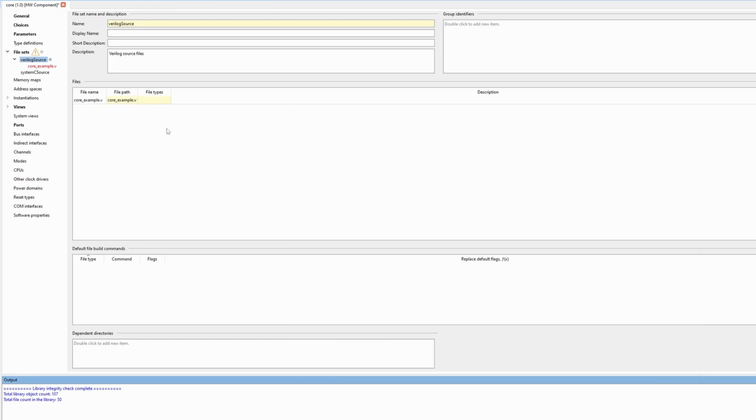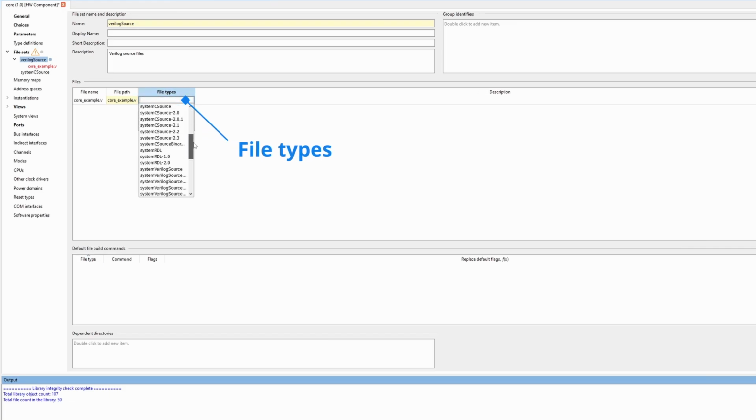Cactus2 creates a new row for the file, and updates the file's relative path. We can also manually create a new row and fill in the file path. The editor recognizes both relative and absolute paths. In addition to the file path, a file needs one or more file types. Cactus2 provides a list of the more common types, but a custom type can be given if necessary.